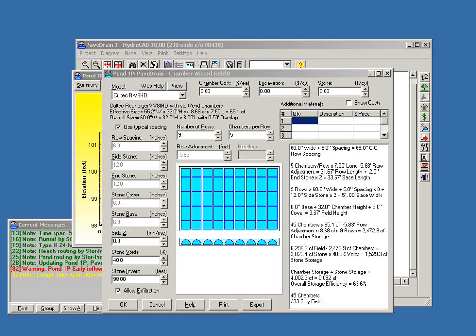You have to account for stormwater because there's no infiltration within those systems. So you have to account for the cost of piping it, buying the land to build a detention pond, excavating out more rock to include underground detention, buying the piping that goes underneath that. All of those things coming into play. And then how about a detention pond's life cycle? Maintenance of that, the aesthetics of it with geese and their droppings and erosion around a pond. And then as a landowner, you've got to pay property taxes on that. Well, the life cycle of that gets very expensive.